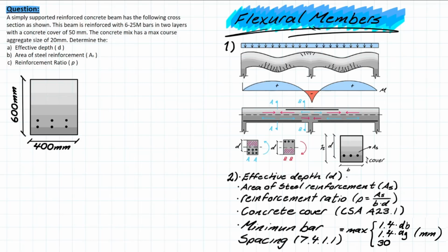So it could be a footing, it could be a beam, it could be a slab. There's many different flexural reinforced members. And depending on where the environment is for that specific mix design, you need a certain cover between your reinforcement. Now, why is that? That's because your reinforcement is subject to damage by corrosion and by infiltration from harmful elements, things like chlorides and water.